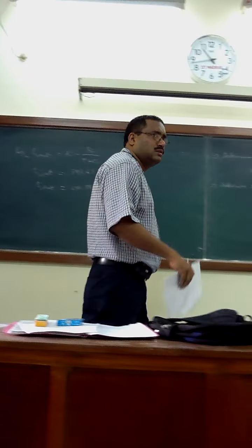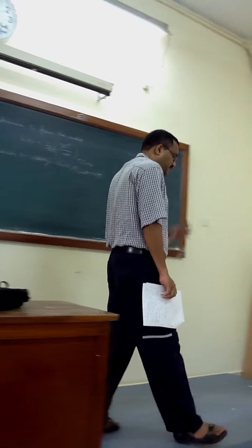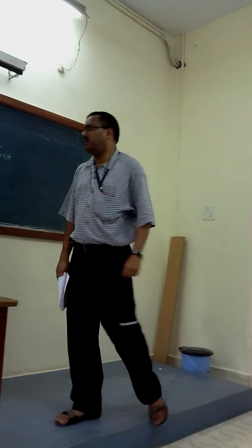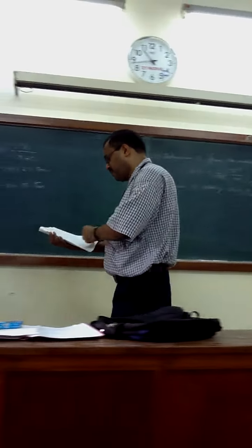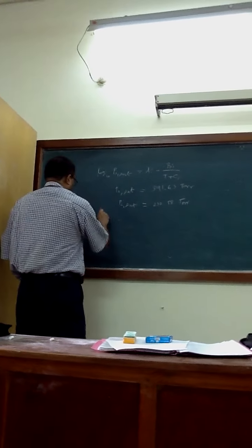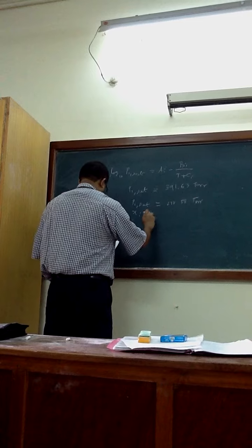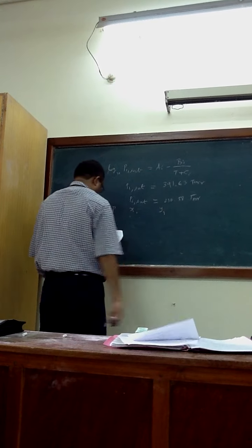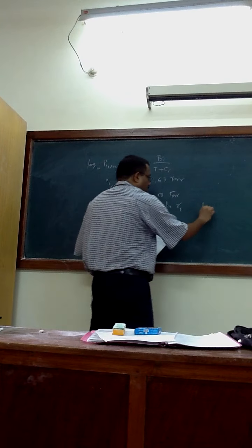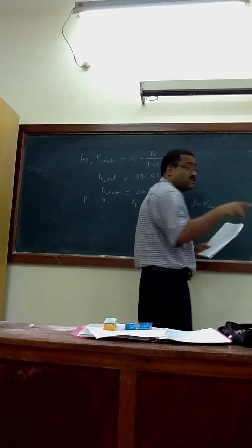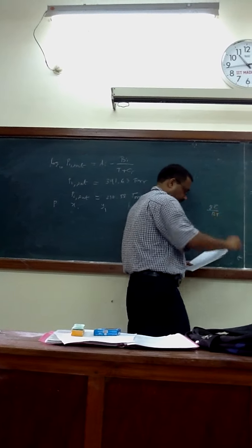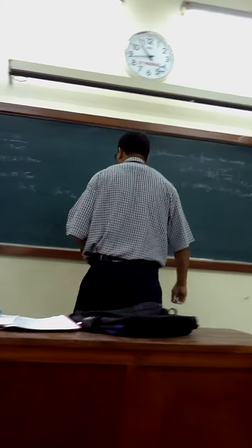Okay. Next step is what? Tell me the steps. We have calculated P1 sat, P2 sat. Is that the end of the story? What will you do next? Your P is given, xi given, x1 given, y1 given. We have ln gamma 1, ln gamma 2, and from the summation of xi ln gamma i, you will get experimental GE by RT.